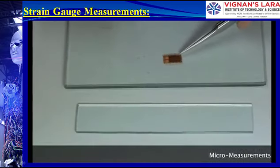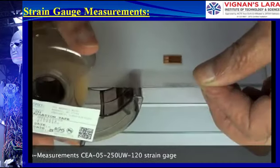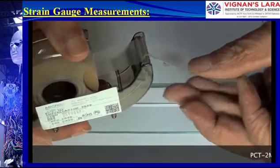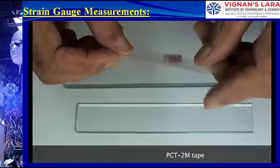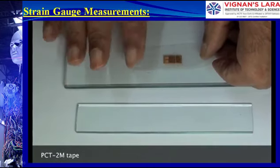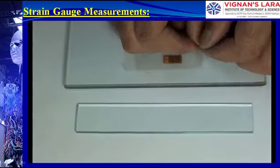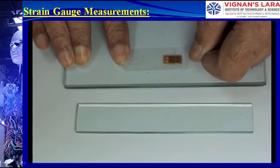To transfer the gauge to the beam, a special tape such as the PCT2M tape is used, as it does not leave its sticky mastic behind on surfaces. A length of 3 to 4 inches of PCT2M tape is laid over the gauge and its edge is folded to make a handle to lift the tape again. The tape is lifted from the glass plate at a shallow angle to minimize the bending of the gauge.